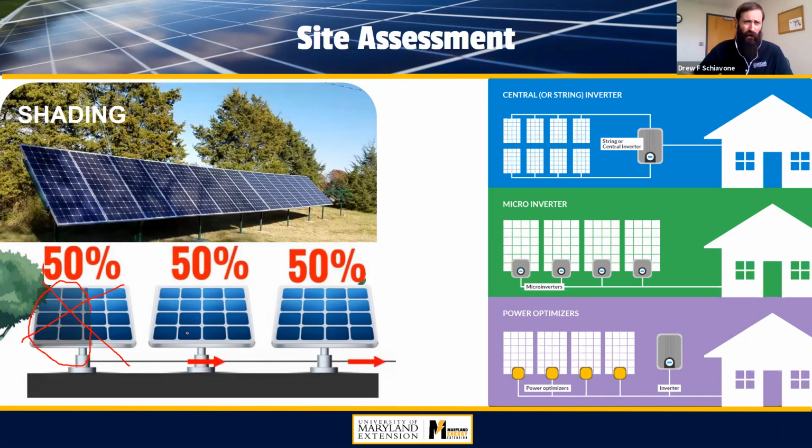It could also be snow cover or anything like that if we have a high snow season. You want to make sure your panel's not shaded or covered in any way. We'll talk about maintenance upkeep with dust and bird droppings and stuff at a later date, but all those things can kind of impact how a panel is producing energy. So as I mentioned, if these are connected in series, what happens to one panel is going to impact the entire series, the entire array.